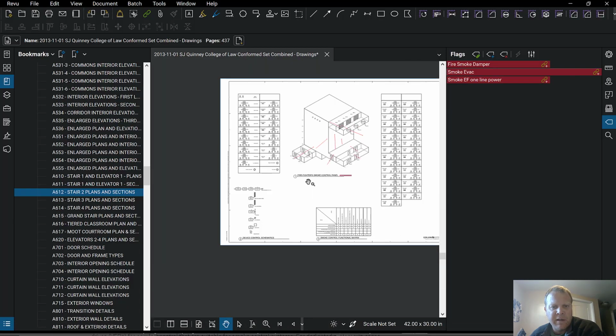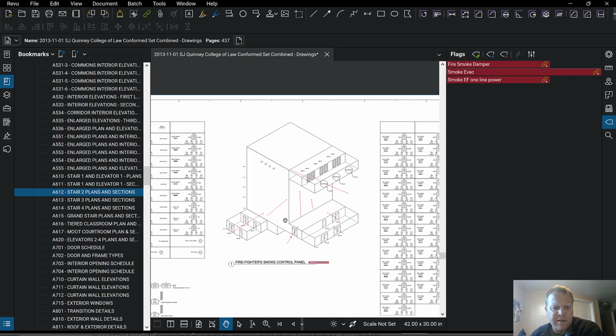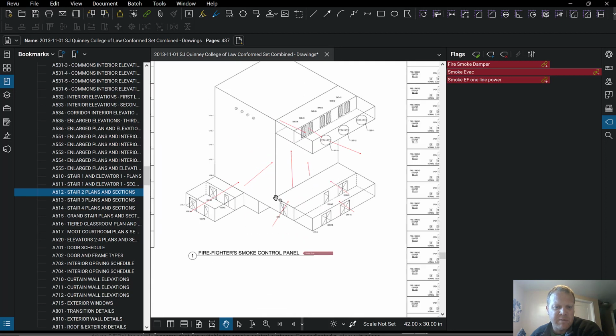we tested individual components, smaller systems by themselves, right? So for instance, we would test out individual doors, make sure all the doors were working, then run all the doors at once, see if they opened up all at once. Yes, they all opened up. Okay, if they're all opening up, let's leave them all open and let's test the motorized dampers all individually, and then we're going to test them all as a group because they're all supposed to open. Okay, we've got those to work.